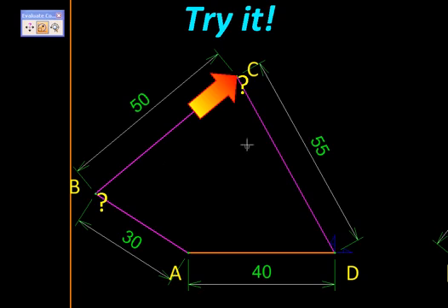The angle between this force which acts along the coupler and the output link captures this ease with which we can overcome the load at the output. This angle is called the transmission angle. The closer it gets to 90 degrees, the more effective is the force we apply.